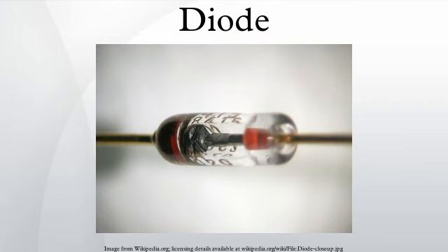Also, following the end of forward conduction in any diode, there is reverse current for a short time. The device does not attain its full blocking capability until the reverse current ceases. At reverse bias more positive than the PIV, there is only a very small reverse saturation current. In the reverse bias region for a normal P-N rectifier diode, the current through the device is very low. However, this is temperature dependent, and at sufficiently high temperatures, a substantial amount of reverse current can be observed.